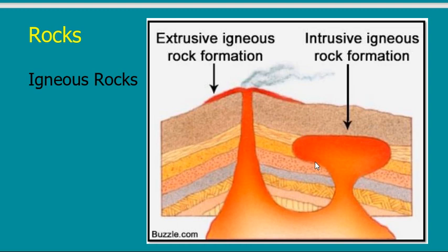As a geotechnical engineer, imagine that you want to put your building here and you made a site investigation. When you do a site investigation, you are going to drill boreholes. Once you drill the boreholes here, you will find that you touched the rock. Okay, I'm fine, I reached the rock. I will stop, this is good land. I reached the bedrock. But actually, is this the bedrock? No, it's not the bedrock. It is just a piece of magma that came from outside and just cooled at this level.